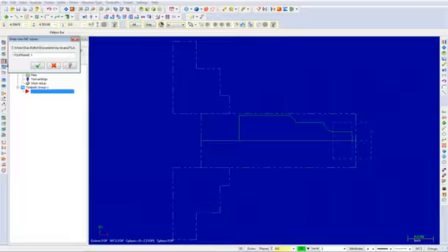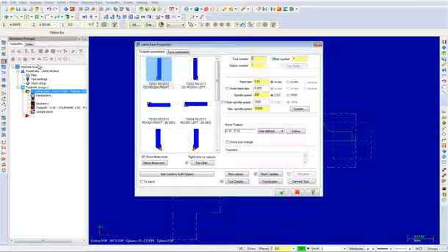Select the OK button to accept the NC name. From the tool list, choose the OD Rough Right 80 degree tool and input the comment "Face the part." Now, select the Face Parameters tab and make the necessary changes as shown.